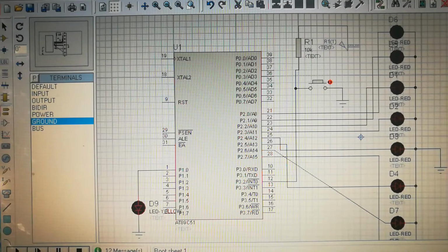So today I will tell you how we can use external interrupts. If you are not following my tutorials, just visit my channel and you will see I have already covered a lot of interfaces with 8051. In the last video tutorial I covered how we can use timer interrupts, which are a software interrupt. In that case, whenever the TF flag bit becomes 1, the interrupt signal is generated and it jumps to its ISR.